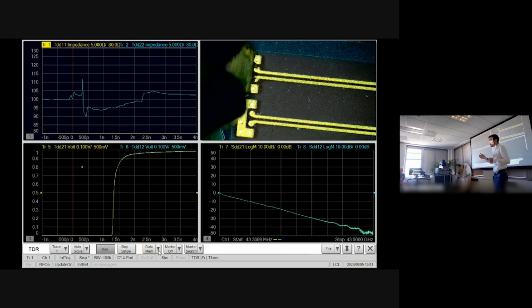Okay, possible. So the important point to remember here: interpretation of TDR plots is not as straightforward as it looks, because what you see, this impedance here, is when looking through the same transmission line that you try to characterize. So loss, for example, generates a slope. Okay, but I think it was too easy to understand that there was a catch somewhere. Nobody dared to say it's the same. Let's see, Marcel. Yes, please. And indeed, it's mirrored.